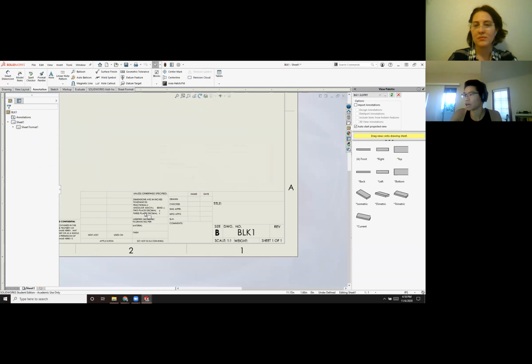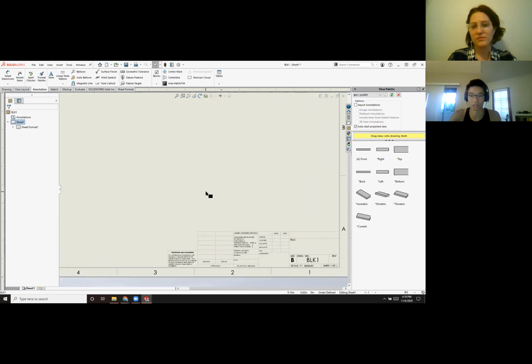As you go on through engineering, drawings are used very, very heavily to deal with machine parts for 2 reasons. One, it's a very easy way to distribute an unchangeable referenced version of a part that you want machined. You can give that to, for example, a machine shop, or to your producer or supplier and have them make those parts for you without having to give them access to your SolidWorks files, or transfer those files around and lose track of them.